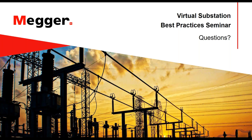So great question. If you look at IEEE standards, C57.12.00 or 12.90, the winding resistance and TTR tests are routine tests. What that means is that the test is applicable to all types of transformers. So even if it's a new design, or a new transformer, or even if there is field testing, these tests have to be performed or are recommended for all those scenarios.